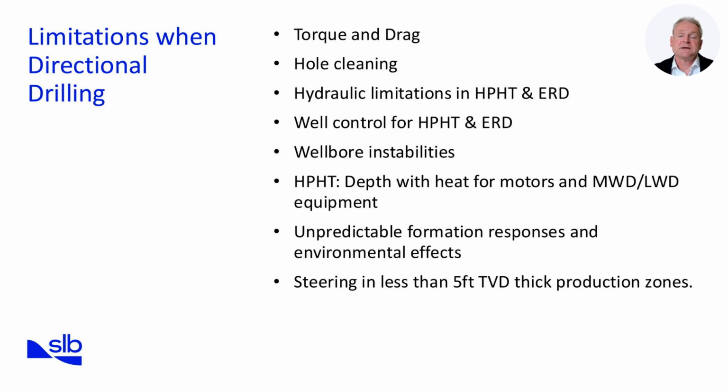6. HPHT tool limitations. Downhole tools, particularly MWD, LWD sensors and motors, are often limited by thermal degradation. Temperatures above 150 to 200 degrees Celsius can compromise electronics, elastomers, and batteries. 7. Unpredictable formation responses. Even with pre-drill models and offset data, formation responses can be unexpected, whether it's lost circulation, overpressured zones, or faults. 8. Steering in thin zones less than 5 feet TVD. Geosteering in very thin reservoirs, often under 5 feet in true vertical depth, is highly challenging and requires a high degree of skill.